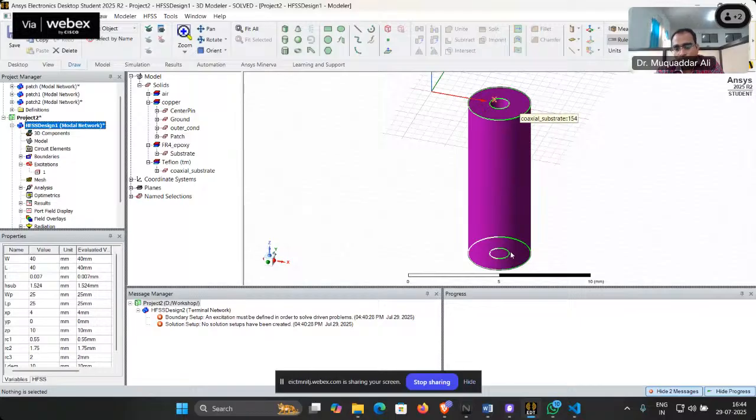Okay. So if we are connecting our device in the VNA, then the length of the transmission line that we are using will affect our results. So in order to make sure that our results do not get affected, we need to match the antenna terminal to 50 ohm, because most of the coaxial lines are of 50 ohm.